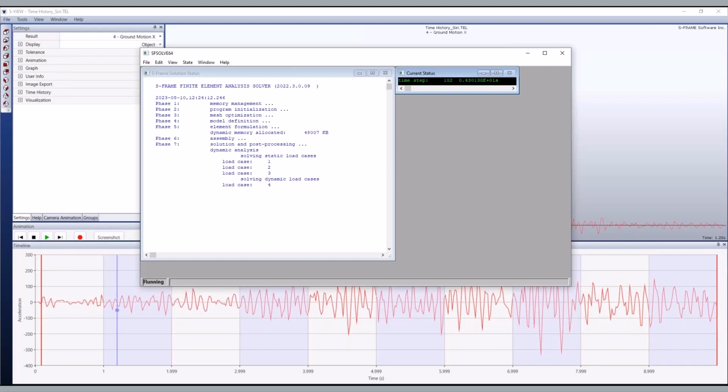You will notice how the time steps will cease to be generated much earlier this time. We won't be reaching 2000 by any means, as we explained before. We won't be looking at a defined number of constant time steps, but S-Frame will be looking for the variations in acceleration to plot a more accurate curve, like the one we showed right before the demo started.